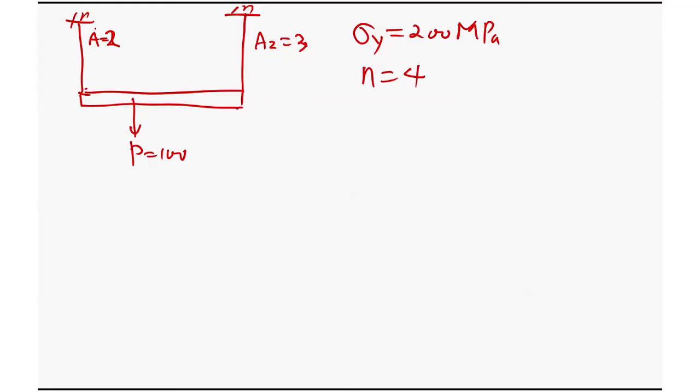So now applying this load here. All right. So my question is, if I apply this load here, it will be shared by these two cables for sure, right? You all agree on that? And then, are these two cables safe enough to carry this 100 pounds? Let's make it 200 Newton. Make it easy, just all Newton. Okay, these are millimeters. Millimeter square, that's the area. Okay. Is this structure safe enough?